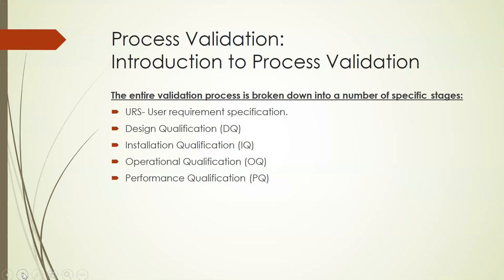The installation qualification confirms if the equipment has been installed correctly. The operational qualification ensures the process input parameters are adjusted to obtain the correct output from the process. The performance qualification ensures that the process consistently meets the customer requirements. This is a summary, and the course will go through each step in more detail.